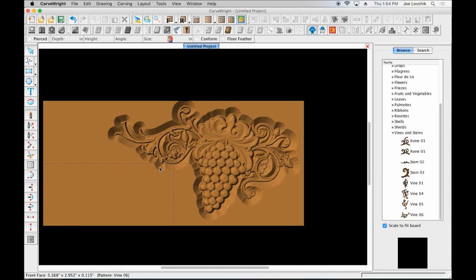So another thing to consider when doing carvings, especially one that's this small, is that 1/4 inch is actually pretty deep for something that's only 5.5 inch by 12 inches and is going to take more time to carve, because every amount of material that's got to be removed is time that the machine is going to take to do so.